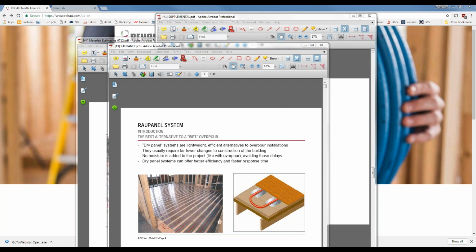Yeah, that's one of the disadvantages of the aluminum heat transfer panels: you basically have to have access to the subfloor, and it has to be relatively clean. If there's flooring installed above where there are nails and whatnot coming down, it might not be the best application, because in order for the heat transfer panels to add any benefit, they do need to be up against the bottom of the subfloor snug, so they can transfer as much heat and as evenly as possible into the wood subfloor.